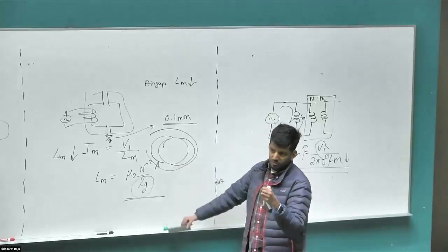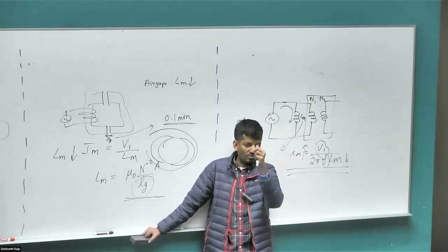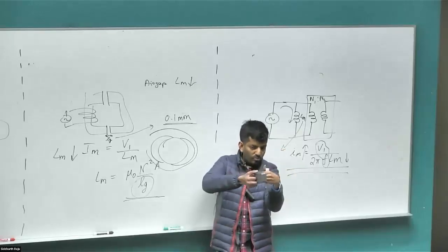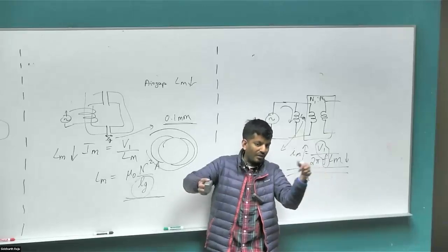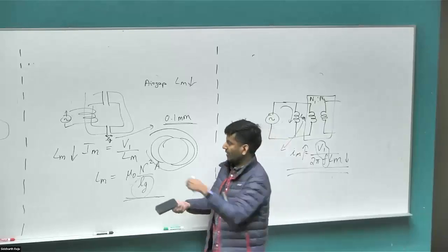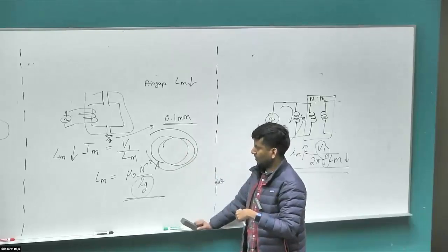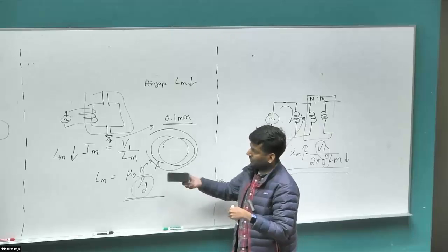One way they get around this is in the hub motors people use in quadcopters. They put the rotor structure on the outside so that the centrifugal force will push the magnets away from the air gap. Magnets are stacked on the outside, or the rotor is on the outside. So the air gap length would actually increase as you go to higher speed so that it won't strike against the stator structure. Right? But in case of an induction motor, we don't have any magnets.